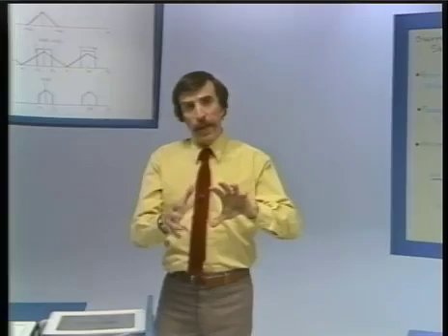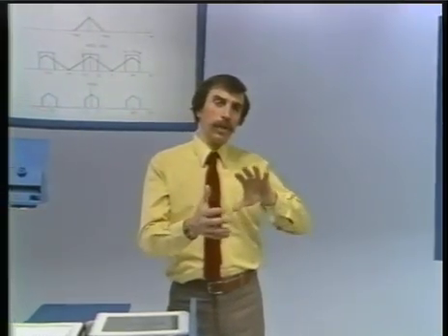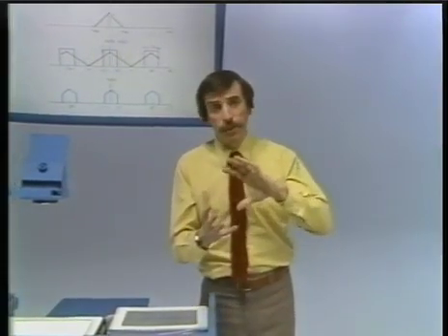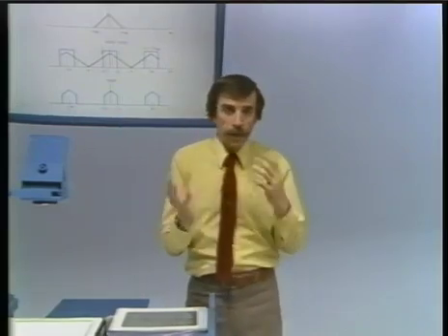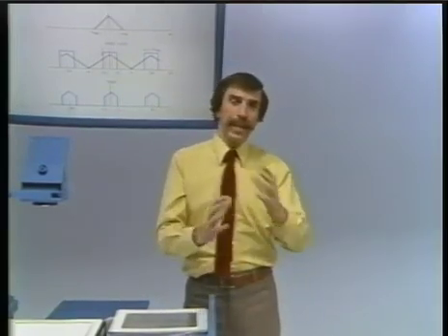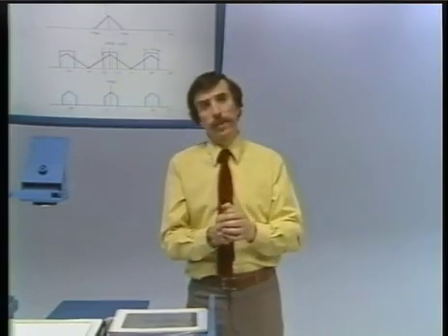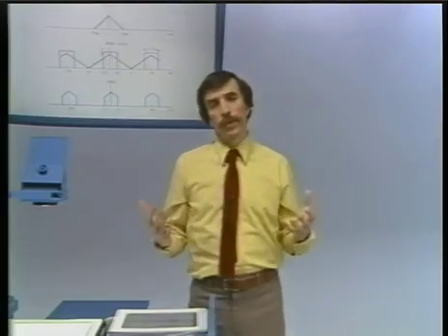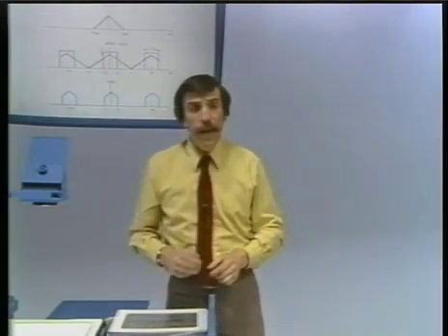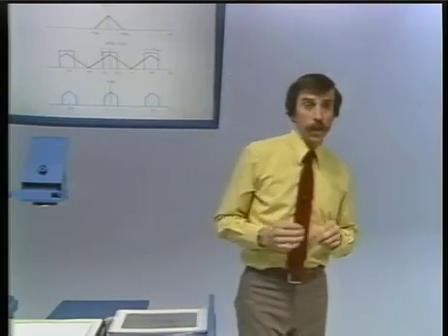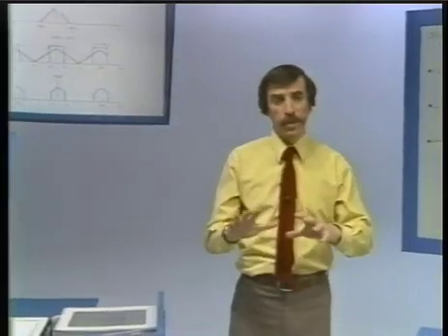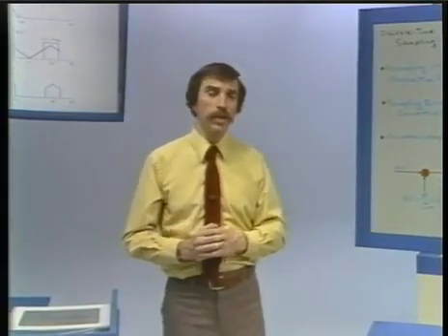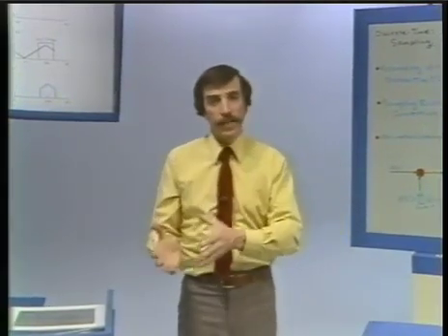OK, so here we have now the notion of sampling a sequence, and very closely tied in with that, the notion of decimating a sequence, and related to both of those, the notion of downsampling, that is, changing the sampling rates so that if we were tying this in with continuous time signals, we've essentially changed our clock rate. And we might also want to, and it's important to, consider the opposite of that. So now a question is, what's the opposite of decimation? Suppose that we had a sequence and we decimated it.